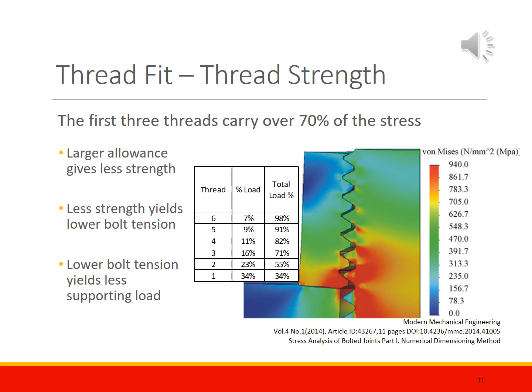Somewhere around 70% or more of the strength of a bolted joint comes from the load carrying ability of the first three threads. This is known as thread stress, and the looser your thread tolerance, the more gap you will have between threads. This gap reduces the overlap of the threads from nut to bolt, increasing the thread stress for a given load, which reduces the load carrying ability. The tighter the fit, the more overlap you get. The more thread overlap, the lower the thread stress for a given load, and the greater the load carrying ability for the bolted joint.